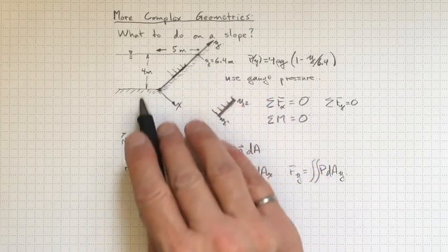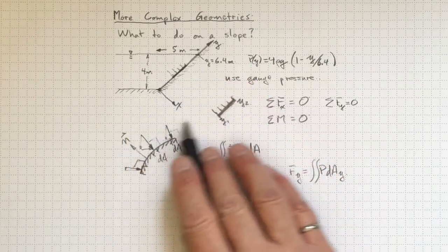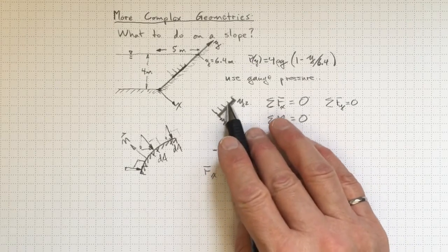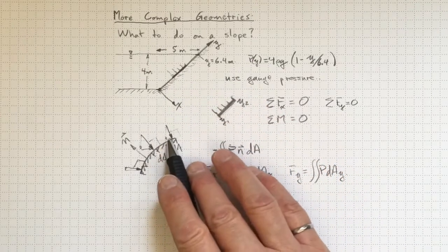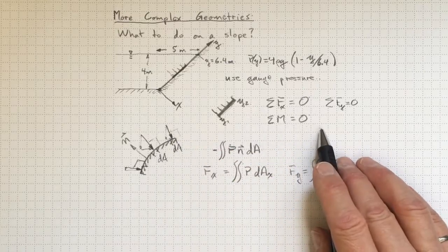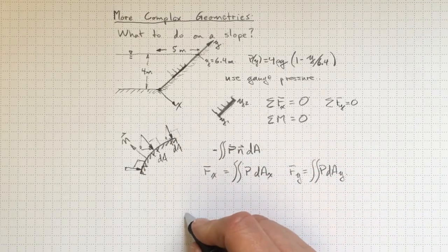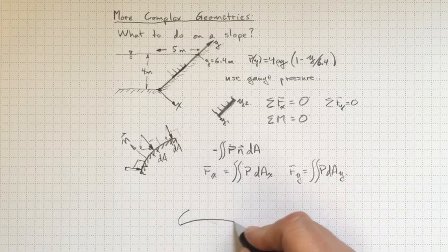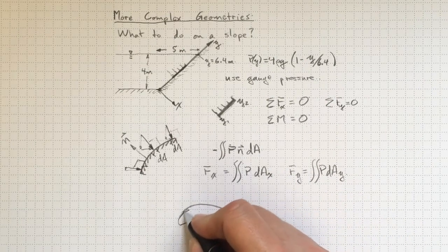So hold on to that idea, and we'll use that capability in some examples in a little while. Now, this will allow us to find pressure forces acting on static systems. This is also going to turn out the same idea of being able to integrate the pressure over a surface to be important later on when we look at airfoils, for example. For example, wings on aircraft or blades on wind turbines, just about any system like that.